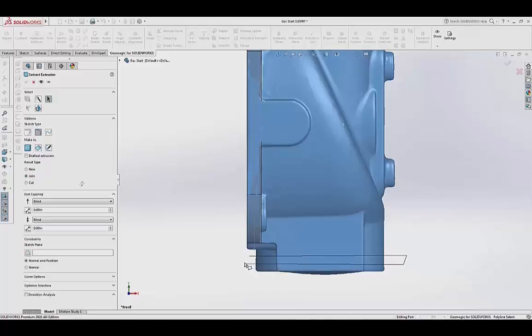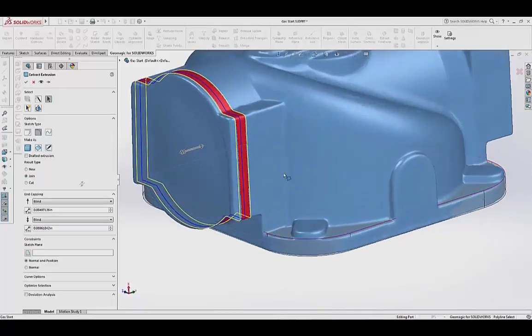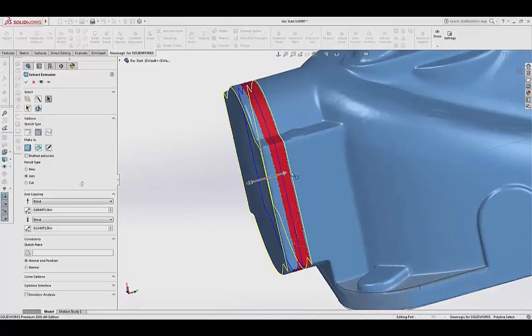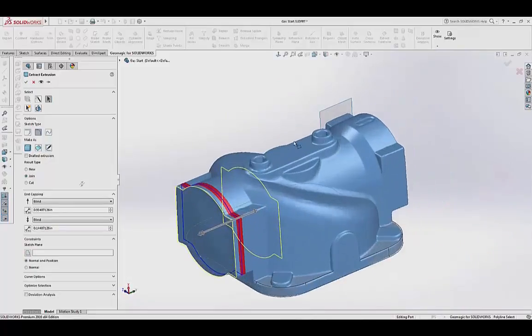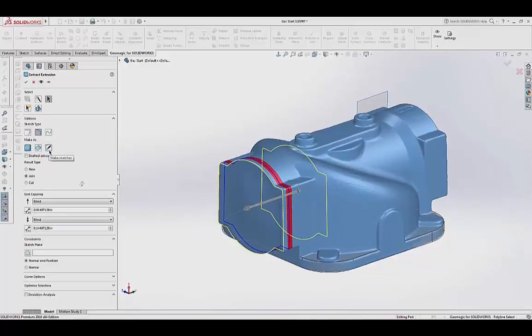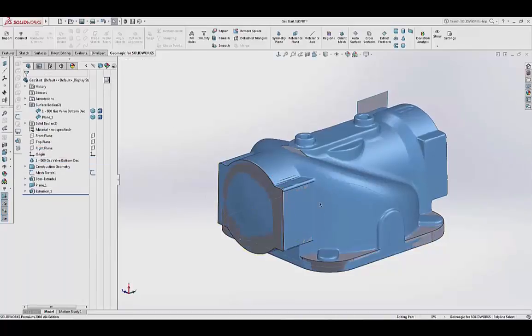If I look at it from the side and create that red selection, the software will automatically calculate the direction, do an auto sketch, and preview an extrusion distance for me. And then I have the ability to edit that if I want to. So you can see I can drag these two handles out and determine how far I want to extrude that. You have different sketch options. It'll sketch in line, arc, and splines. It'll create surfaces and solids, or just sketches. I can cut, I can create it as a new object, or Boolean it with the other one.